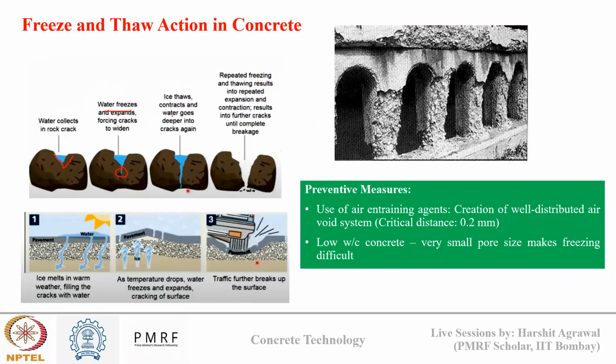When it unfreezes, what will happen? Ice will melt, and due to this, water will be able to go to a deeper depth inside the rock. And then again, if freezing happens, ice will again form and generate expansive stresses inside the rock, and cracking will further continue. This cycle of freezing and thawing will be repeated until there is complete breakage of the rock that will appear like this.